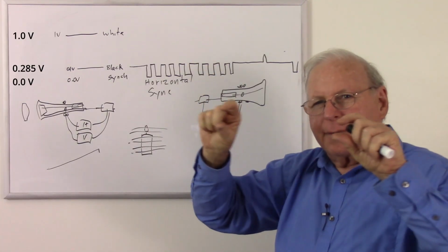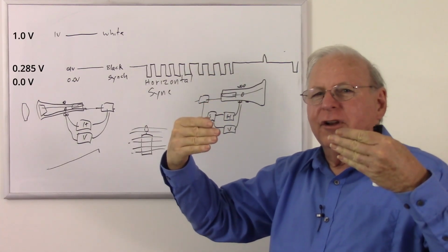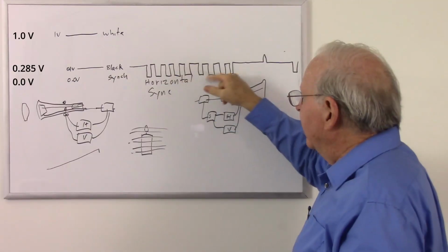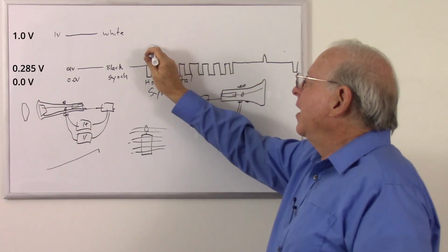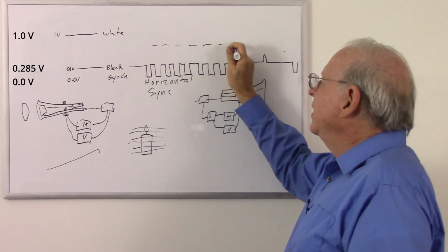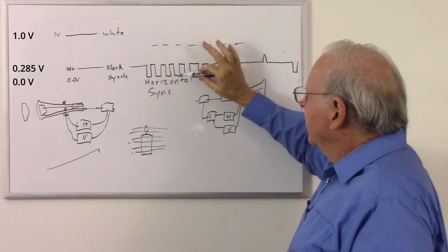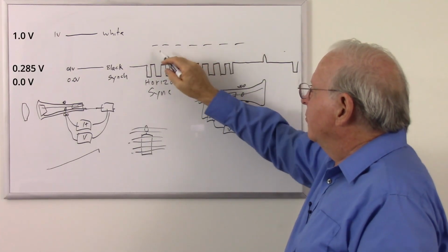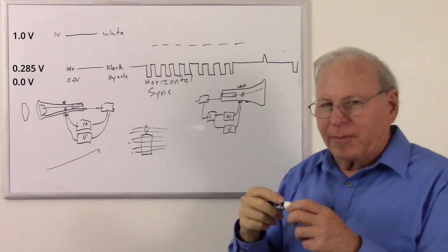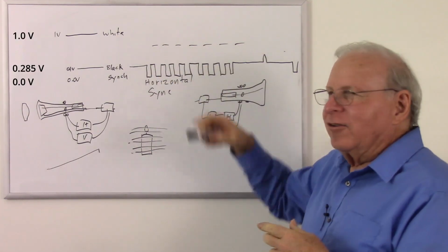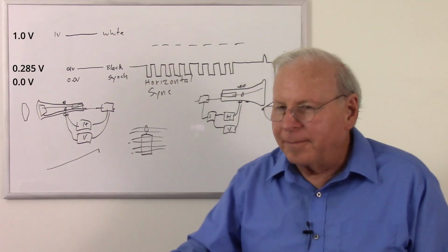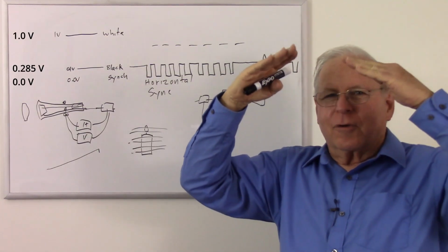And you see this big black bar go through, which was the darkness during the vertical blanking cycle when all that stuff is happening. In fact, you could actually see little lines on the screen, which were how those showed up on the screen, and you'd see a whole bunch of lines and other information. And later, when closed caption was put in, you'd see the digital information for the closed captioning in there. But you get these black bars that would start rolling up or down the screen.